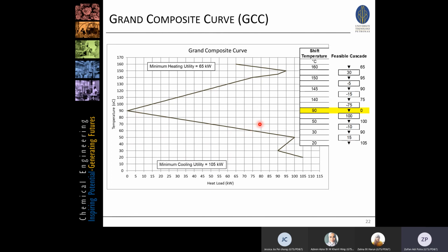So we can have this as another heating medium somewhere, which we can export or whatnot. At least we can generate 60 until 90 degrees C of hot water if there is an opportunity to do so. And then the rest we can send to the cooling tower. And how about this amount of energy? How about this pocket? The heat that needs to be removed here can be used to heat the stream that is coming down, over here.